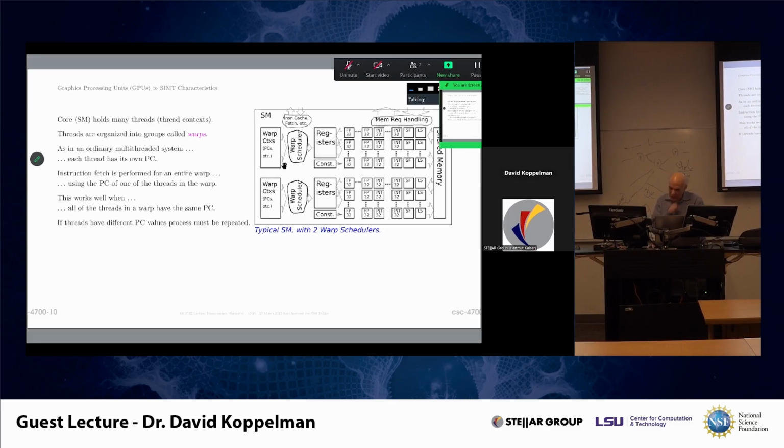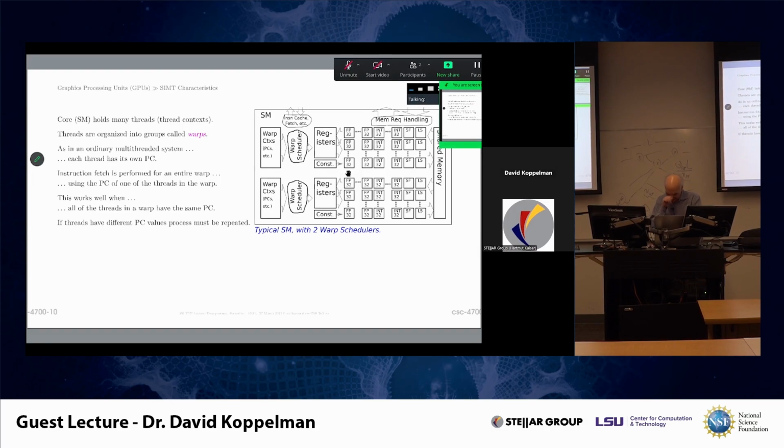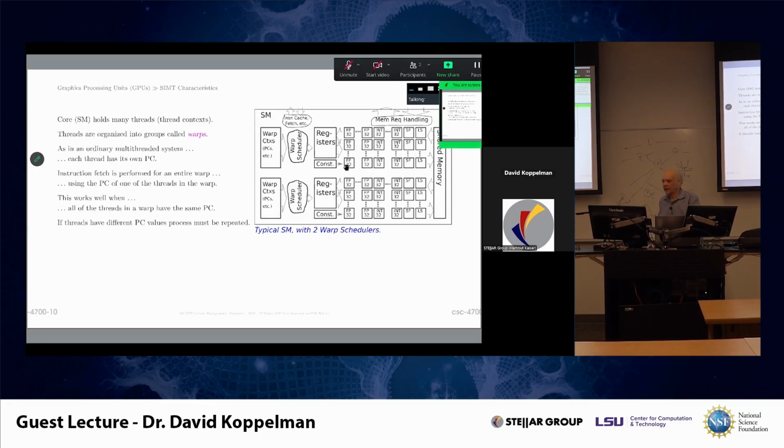All right, so here's what's happening. A warp scheduler picks a warp to execute. And in the warp, there's an instruction. Hopefully, all of the threads agree on that instruction. If not, well, you have to pick an instruction from one of the threads. It executes. And then in each cycle, the warp scheduler is going to pick a warp. It'll dispatch the threads.